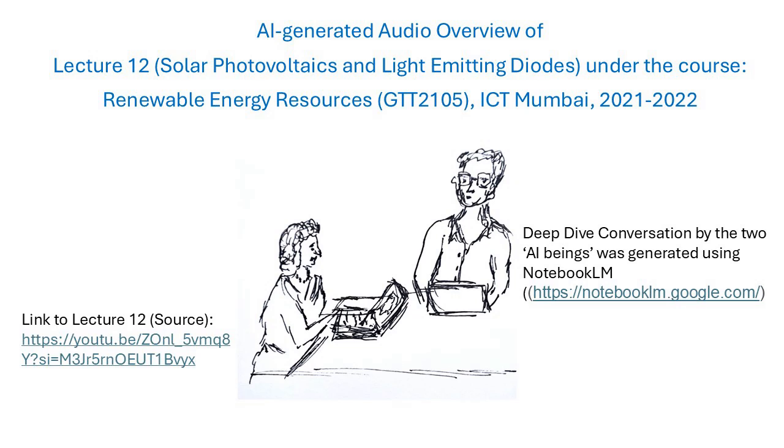So sunlight photons hit the silicon, especially in or near that depletion layer. If they have enough energy, they knock an electron loose, creating an electron and a hole, the spot where the electron was. Electron-hole pair, right? Exactly. And that built-in electric field in the depletion layer immediately separates them. Electrons get pushed to the N side, holes get pushed to the P side. Okay, separation is key. It is.